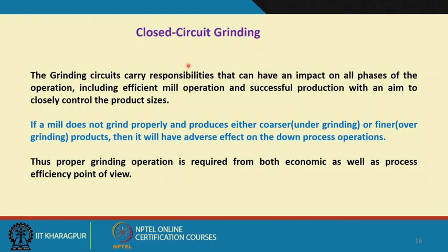We have already discussed it during the topic of hydrocyclone operation, and during ball mill operation or grinding in general. Even closed circuits, we discussed closed circuit crushing, but here I will give more emphasis on closed circuit grinding. So, why do we give more emphasis on closed circuit grinding?